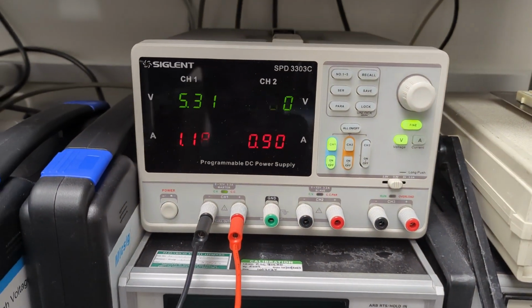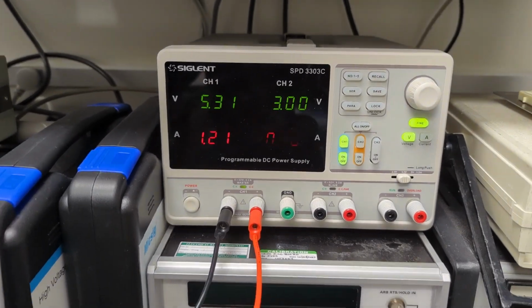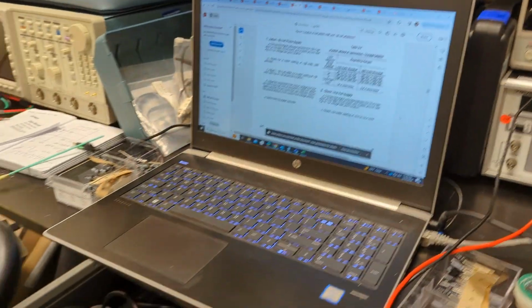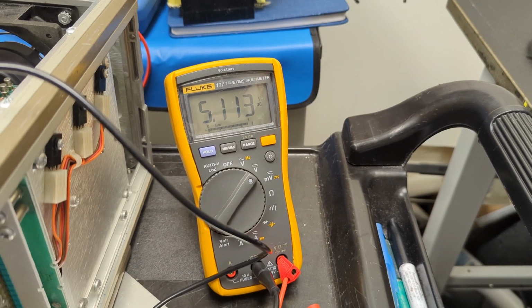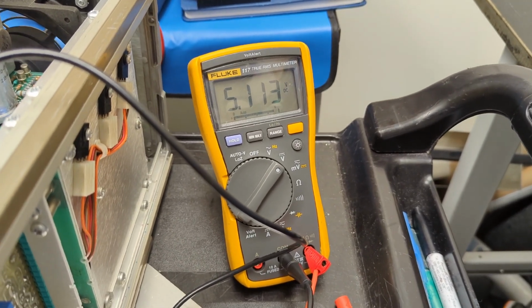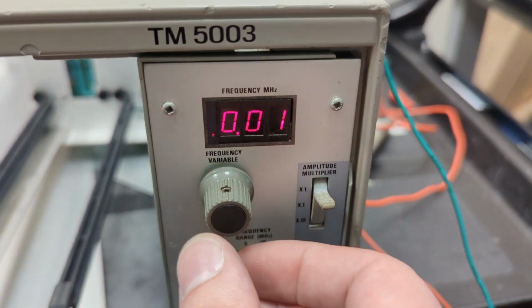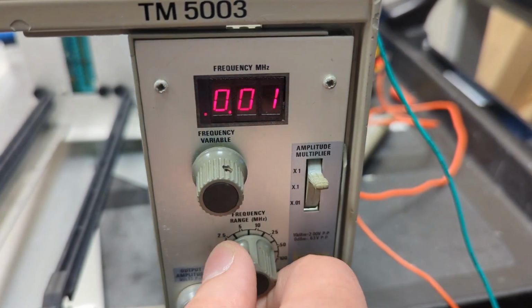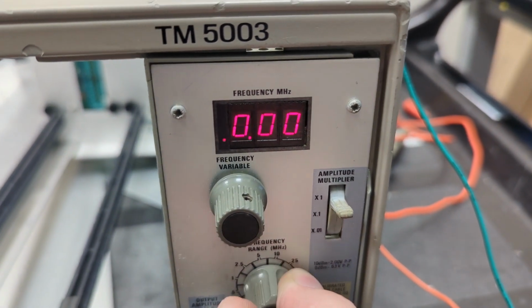Well, I decided to just inject about 5.2 volts into the unit just to see if that would fix the problem. And so we got about 5.1 volts, and that's okay per the service manual. That test point can be between 5 and 5.4. So that's fine. But it hasn't fixed our display problems. It's no different.